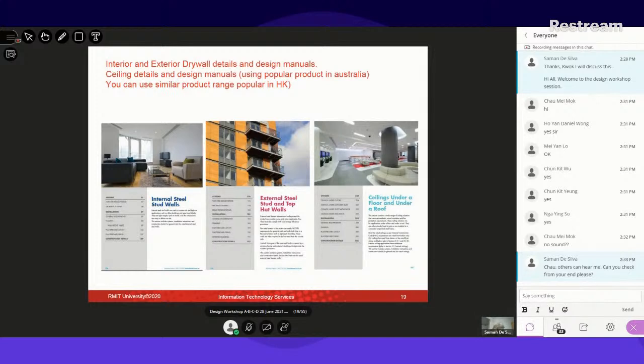The other thing is, a lot of students in your assignments assume those black colored walls are perfect lines. They are not. They are concrete structural walls, and unless of course you pay a huge amount, they will not be constructed to a precast quality, which is S3 quality of surface. The surface is very rugged. It is not smooth. You can't simply paint over it.